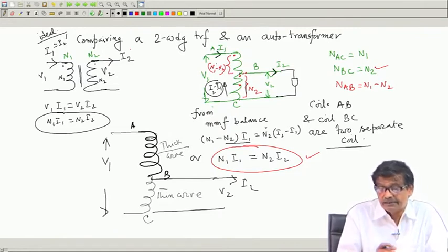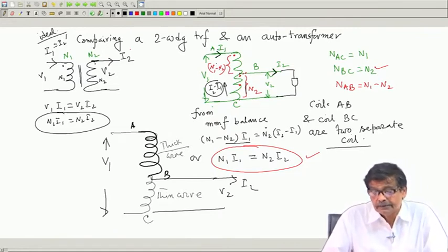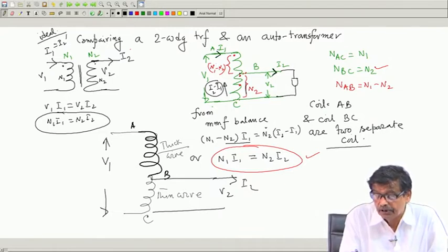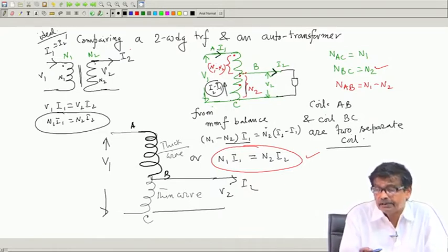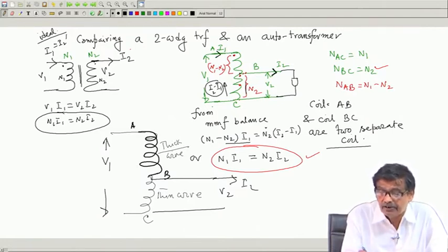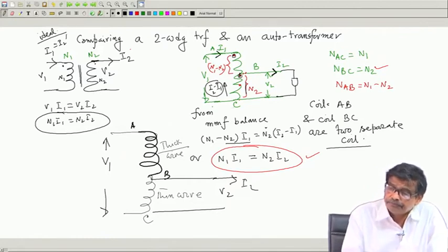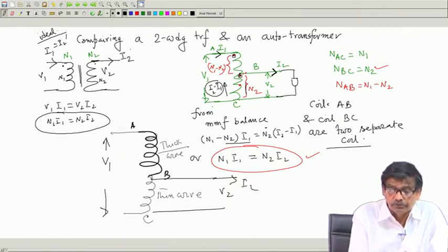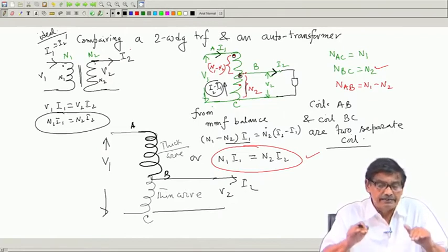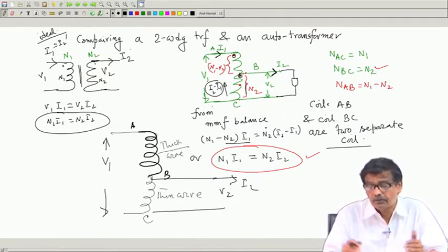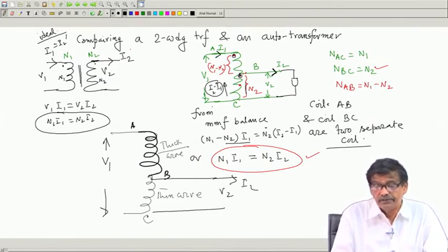They are that way similar, but here you note the current supplied to the load will be I 2, because in an auto transformer there is a common portion of the winding, and this is dot, this is also dot here. Therefore, this current should be I 2. So, we must bring them to the same platform before comparing: same kVA rating, same voltage ratios and so on.